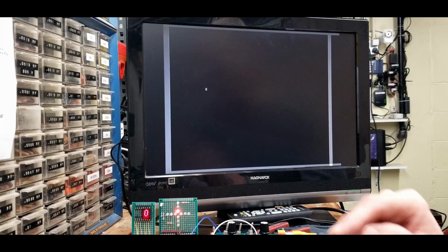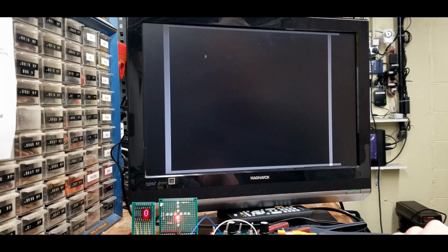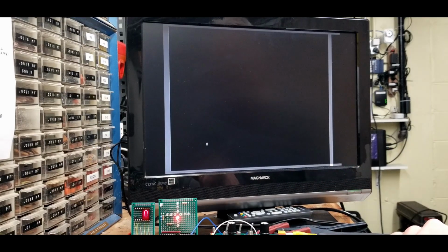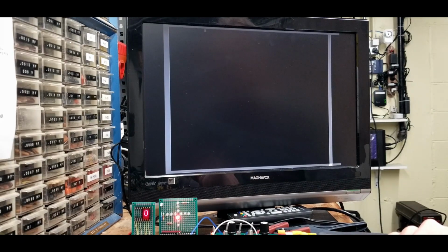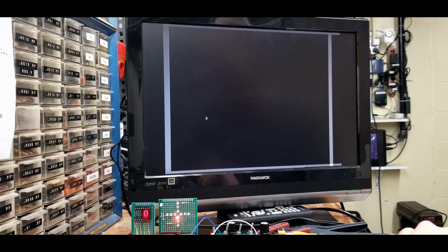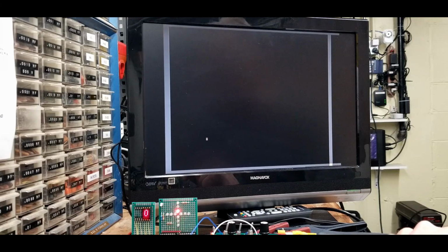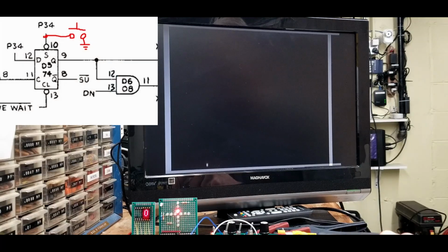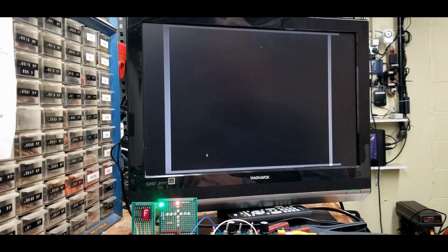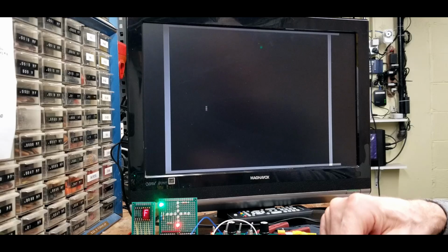To get fast speed, V-slow needs to be off. You remember that V-slow comes from the volley counter's D output when the counter reaches 8, but since we're not moving horizontally, the volley counter doesn't step. We could switch the counter clock to the Y2 output, but the easiest thing to do here is just trip the speed up latch, which turns off V-slow. Vertical motion now stays fast, even if I set and reset the top latch.